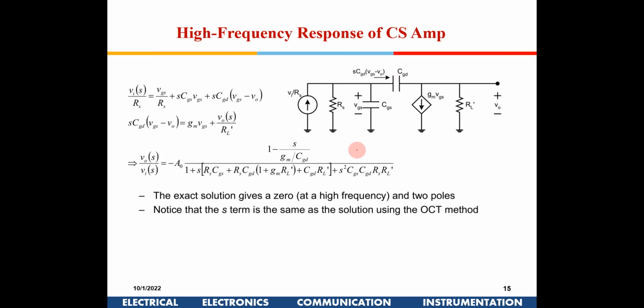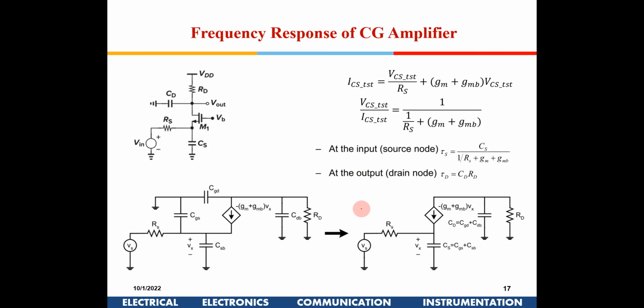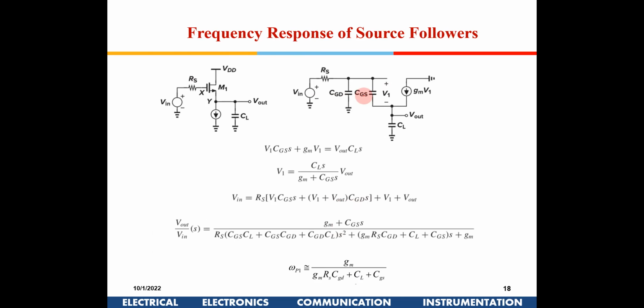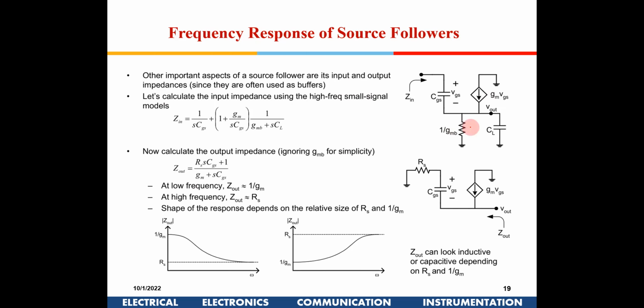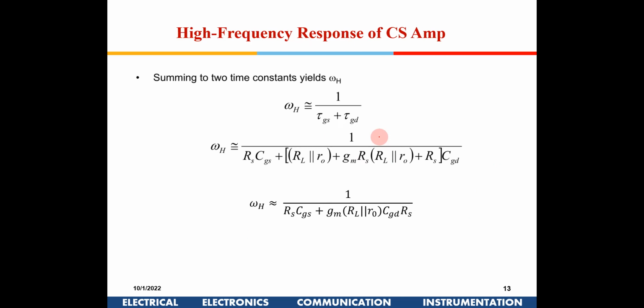Here these two together are forming a single pole only, because these two capacitors can be considered as in parallel. There could be one more capacitor and one more RC filter in the circuit, like we'll see in other circuits in which there could be multiple capacitances. So these two capacitors come in parallel here, so they form a single pole. But there could be other capacitors. So it is like one filter coming in series with another filter, right?